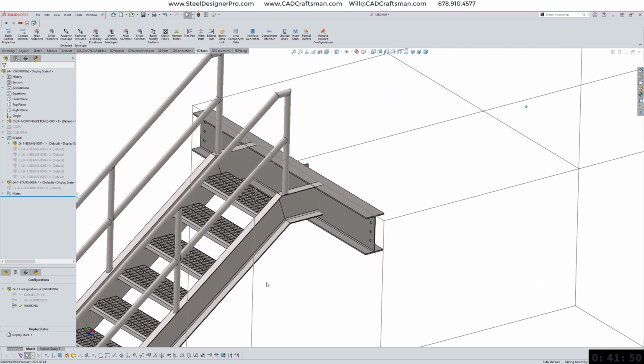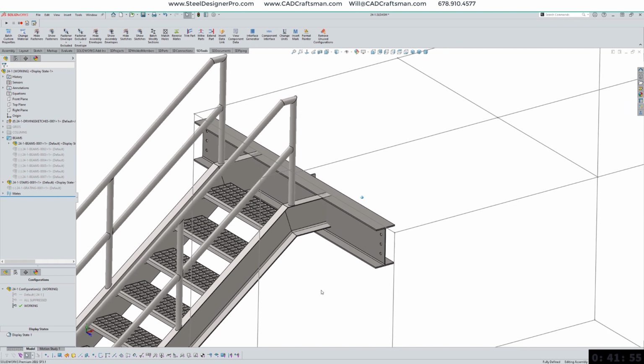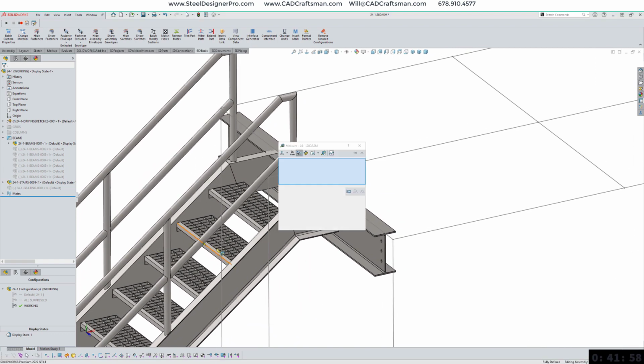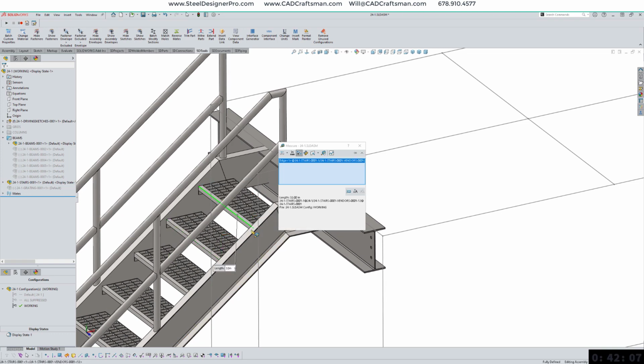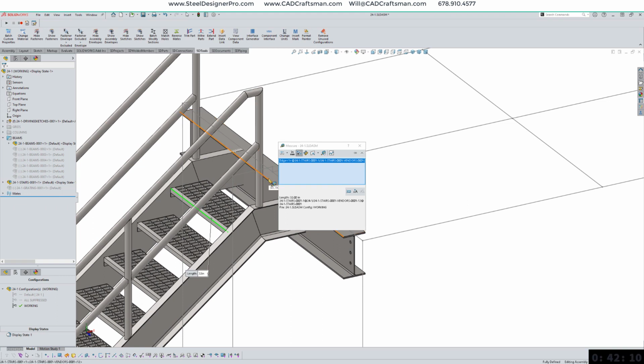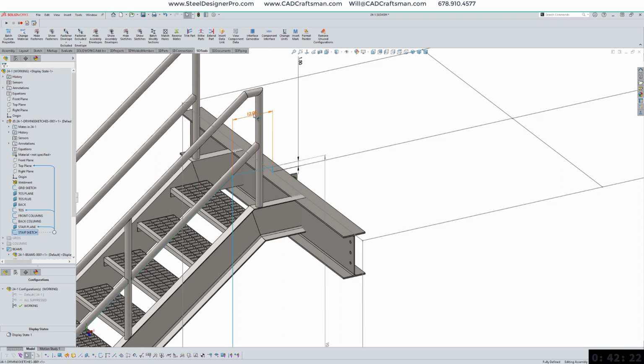We now turn our attention back to the stair. You can measure to see how the equations have created equal rise and run treads. By editing the zone driving sketch, we can adjust the top tread distance to get the correct run. Rebuilding the driving sketch propagates the change to the stair assembly, and through the parametric behavior of SOLIDWORKS, the updates are made.